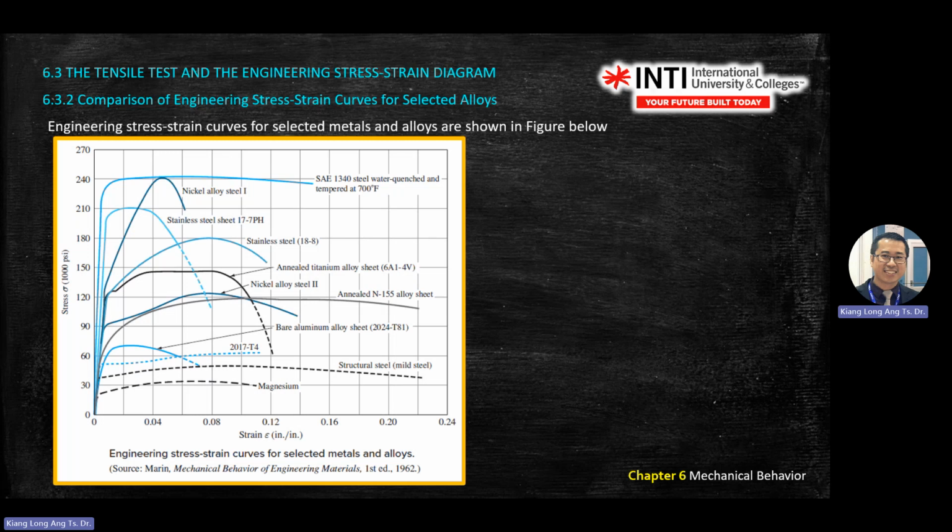So this one smaller gives you higher E, but higher E also means something. If you compare apples to apples, you maintain your stress and look at the strain. If M1 or E1, for example in this case SAE 1340, has a higher E, higher E means a smaller value of elongation ratio. So it means it's harder to change length if you pull.